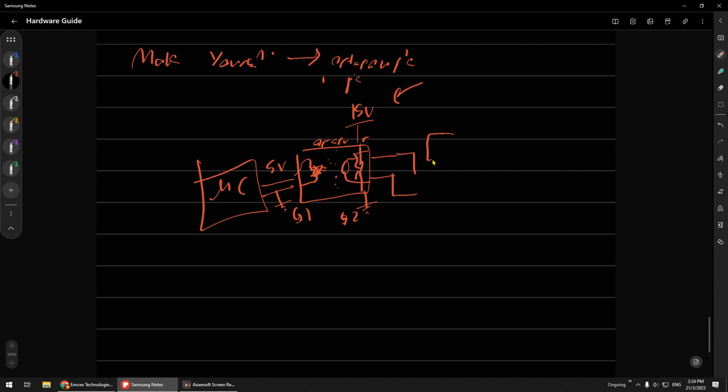Okay, this one connects to the ground, not ground, source. This one is gate, this one is drain. So something like this. Okay, so basically the optocoupler, this one is SCPL 3120. This is the commonly used SCPL. It has an 8 leg IC.